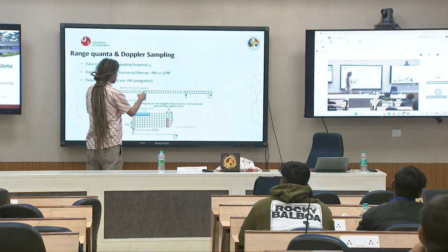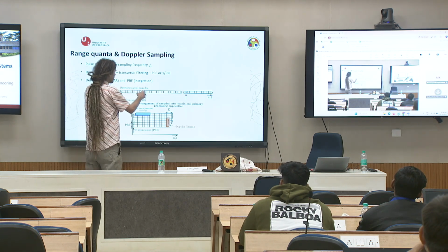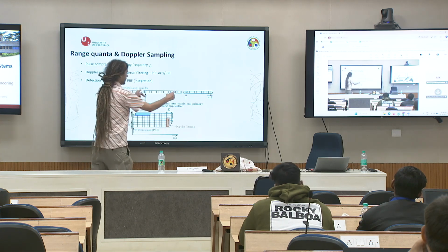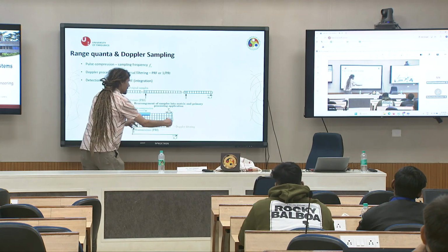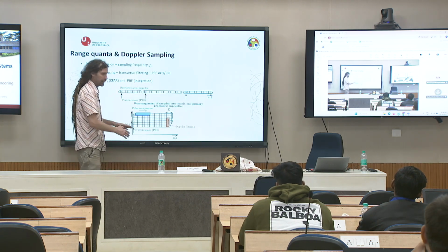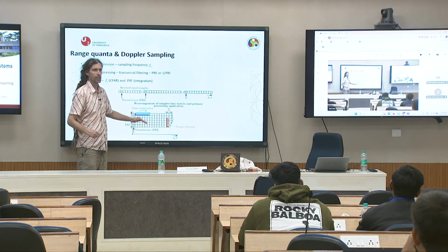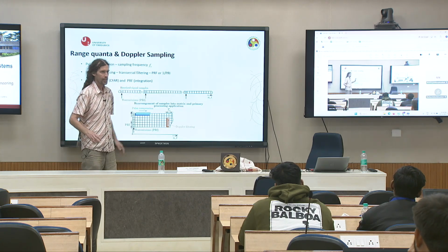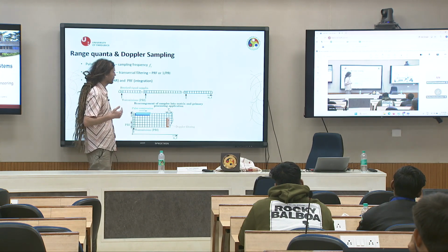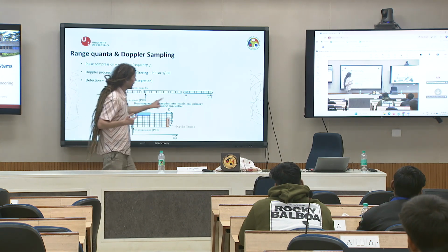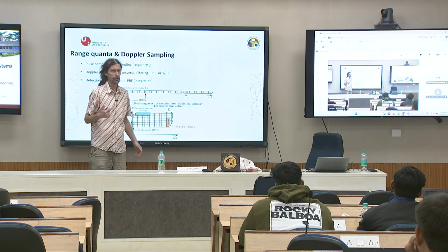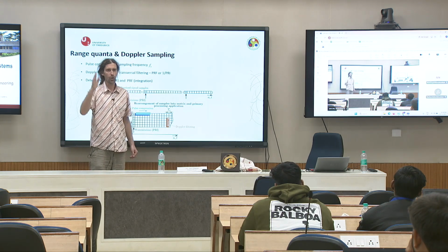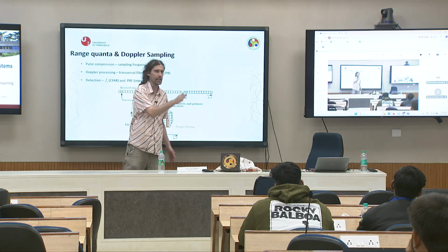I will take, for example, 1000 samples from a PRI, put them there, 1000, put them there, and so on. Is it clear? Of course, this does not happen in reality, because you will continue; you want to compute a spectrum. So you will take 1000 PRIs, and we call it a CPI. It is the coherent processing interval.